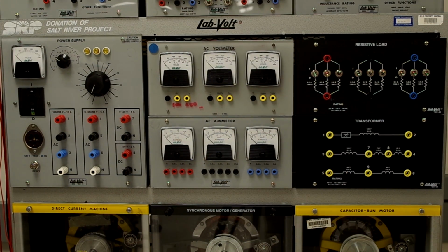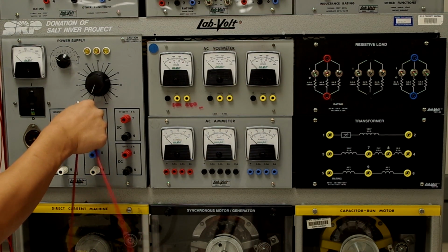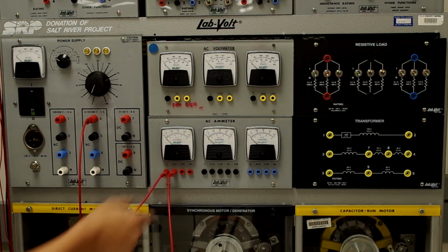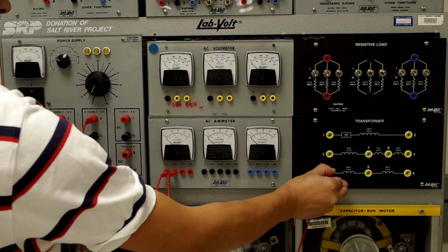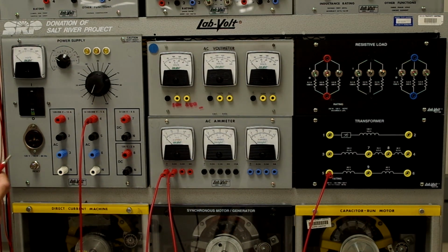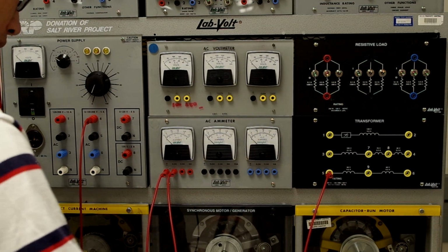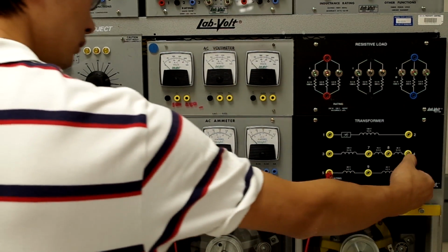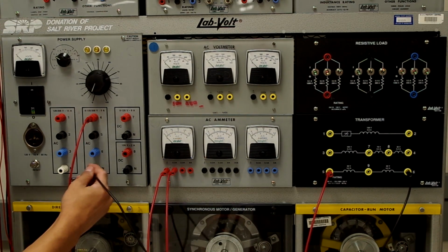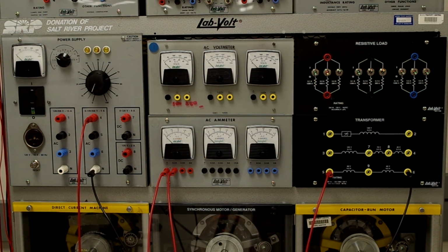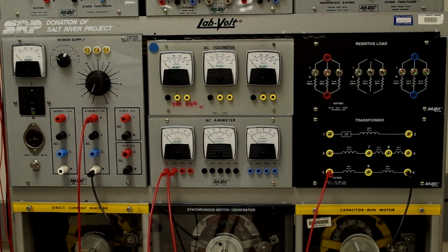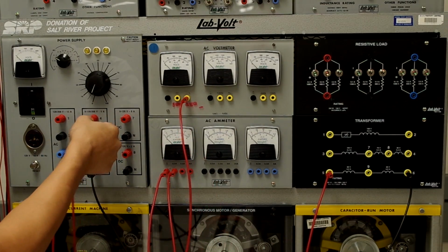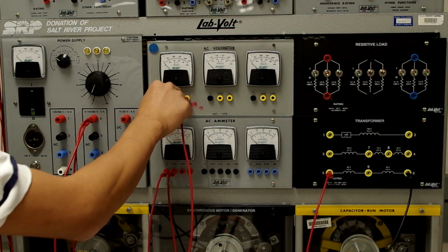Now we're ready to make the connections for the auto transformer circuit. First, we're going to connect from the variable AC power supply through an ammeter, and from the ammeter to the main winding. Then we're going to connect the neutral of the main winding to the neutral of the power supply. Next, we're going to want to check the voltage of the power supply, which will be the main winding voltage as well. So we're going to connect that up. And the other end of that voltmeter is going to be the neutral point of the power supply.